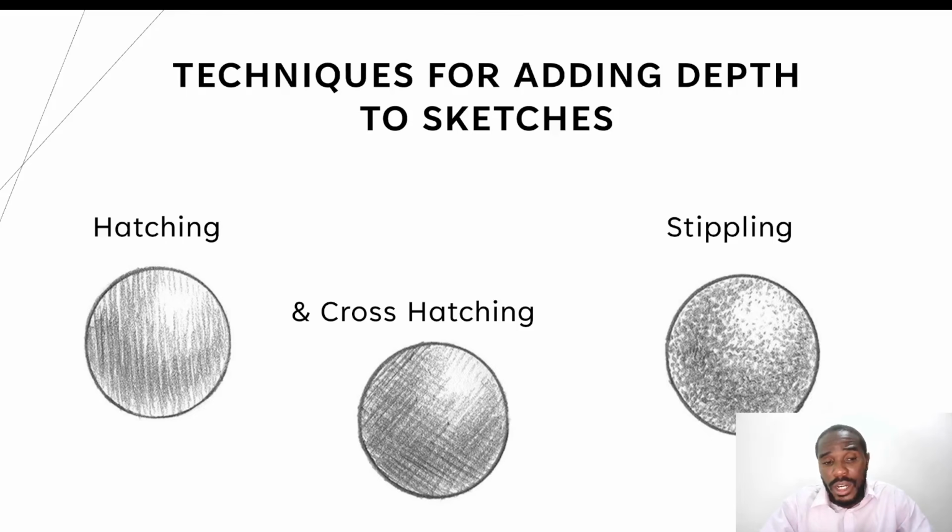And then there's also cross-hatching. Hatching and cross-hatching actually go together. For hatching, all your dense lines are in a given direction, the same direction. In cross-hatching, you have a set of lines that cross each other at an angle, usually 90 degrees, could be any angle at all, okay? So you first hatch and then you cross-hatch. You draw other dense lines, not necessarily perpendicular, at an angle to the first sets of lines that you've drawn, okay?